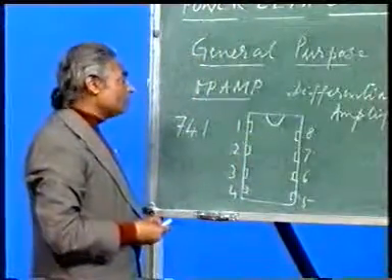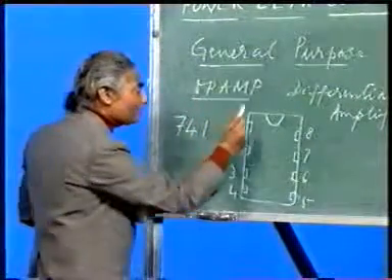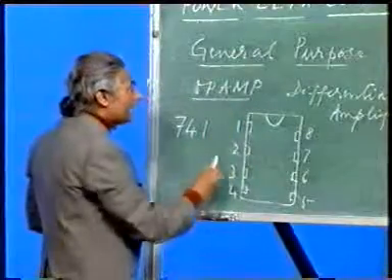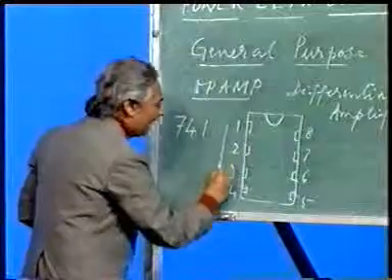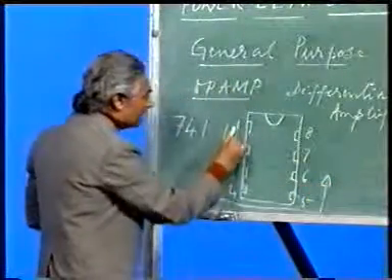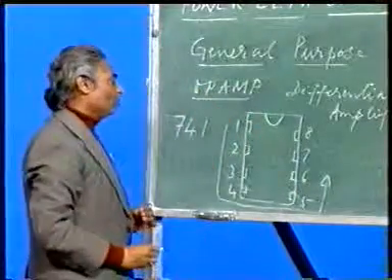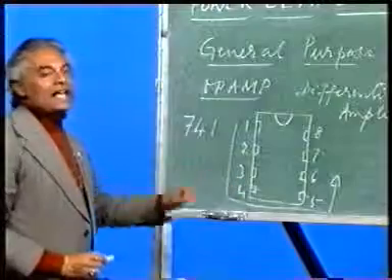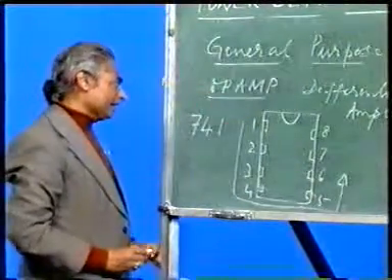Now one important thing is you have to know its configuration. If I have a groove or a dot, I will put it like this, so that the first terminal will be 1, and then we have to go anti-clockwise. Then it will be 1, 2, 3, 4, then 5, 6, 7, 8. Now every pin has a significance, and it is an input or output of the device.